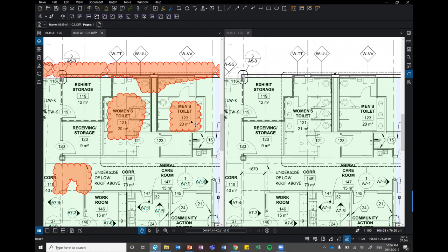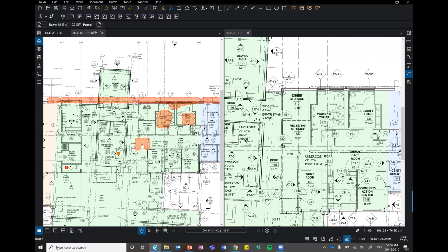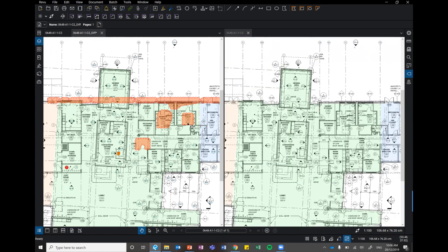So what's worth noting about this tool is it's a really great workflow for anyone using Revit, because you might have drawings you issued, say, 2 weeks ago, a month ago, whatever. They've been issued onto AIConnect or ProjectWise, wherever you're going to. And you made some changes, maybe if it's in AutoCAD. And then you just want to check that all the clouds have been picked up. You can run this process with what you're about to issue and let Bluebeam be the markup tool to say, well, this is where your clouds are.